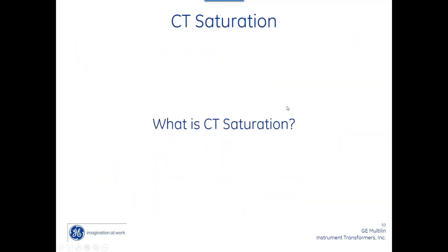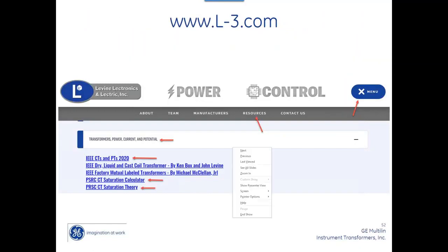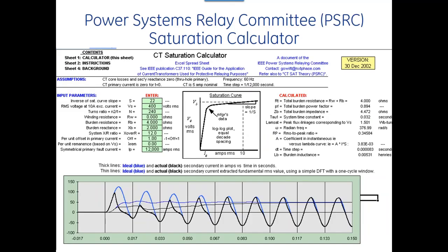Okay, I want to talk about what CT saturation is. A lot of people get mystified by that. So what I recommend you do, and we've got a copy of this on our website, and if I grab the right slide, it's going to be the next one. Yep. Okay. So this is the Power System Relay Committee, the PSRC, came up with a CT saturation calculator. And what you can do is put in all your parameters and determine if this CT is going to saturate or not. So let me show you what I've got here.